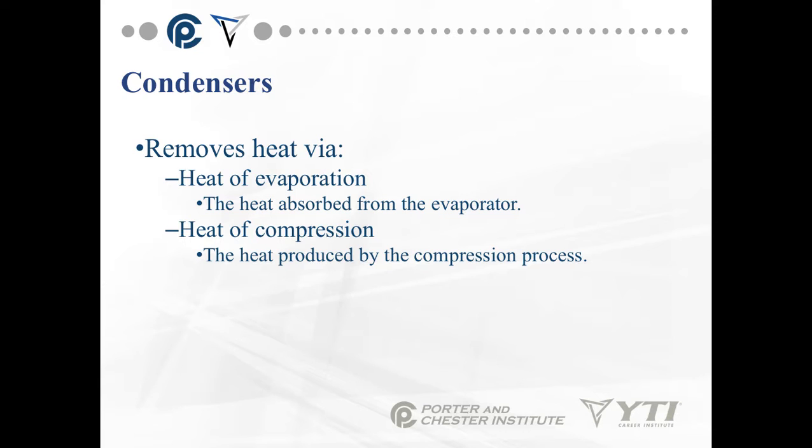Condensers, again, remove heat via the heat of evaporation, that's the heat absorbed from the evaporator, and the heat of compression, that's the heat produced by the compression process. Remember, whenever I press something together, whenever I compress something, whenever I work with a material, we're producing heat. The compressor also produces heat that has to be removed by the condenser because the refrigerant cools the compressor motor windings. So that all produces heat as well.